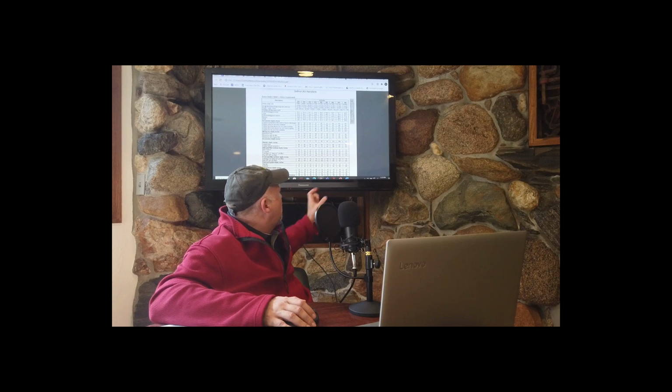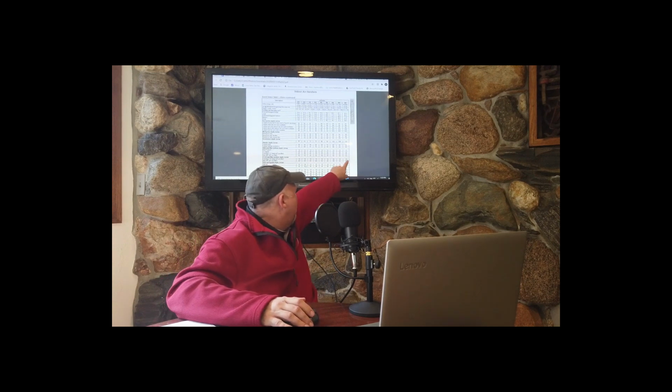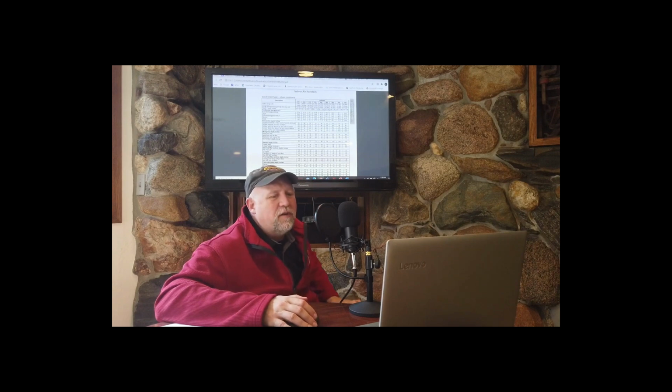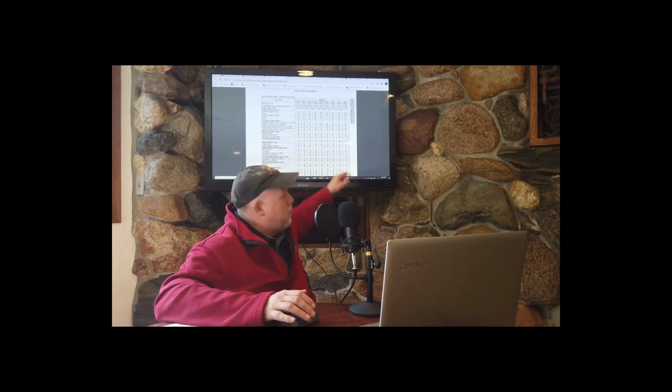And take a look at this. A cartridge filter is 12 inches deep with a 2-inch pre-filter, right? Or a bag filter, which is even longer, 36 inches deep with a 2-inch pre-filter. Now, that ends up being, for a cartridge filter, 16 inches deep, or for the bag filter, 40 inches. Let's go back to our schematic.